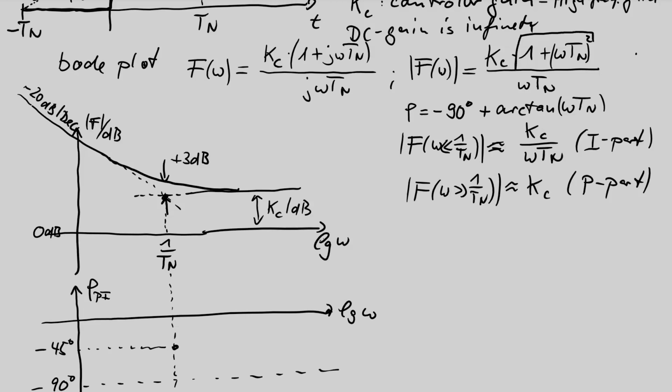So the phase is coming from the minus 90 value through this point and approaching the 0 degree level on the axis. So we have a phase curve. The shape of the phase curve is always identical to PT1 and PD, and this phase is always the arctangent curve, but now shifted into the negative area of the phase diagram. So far.